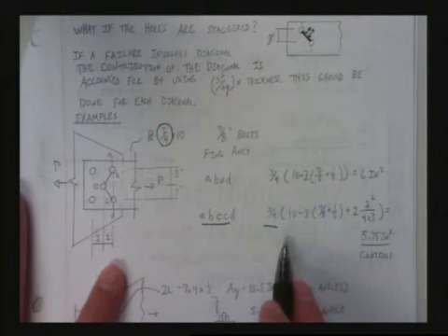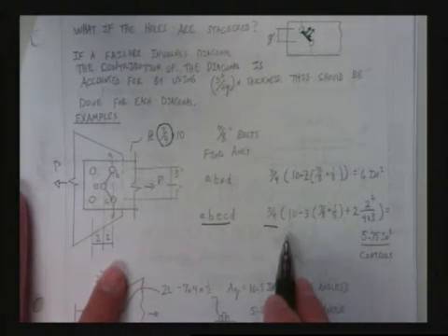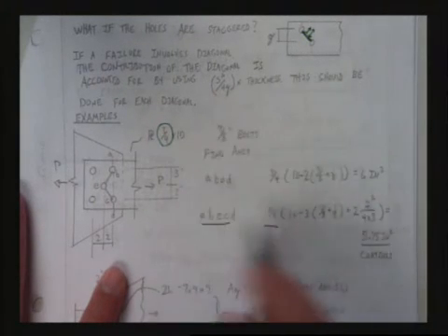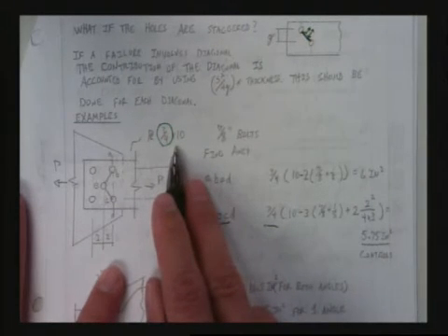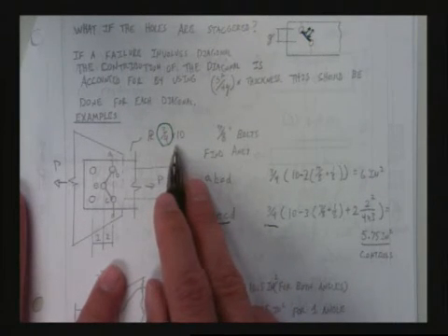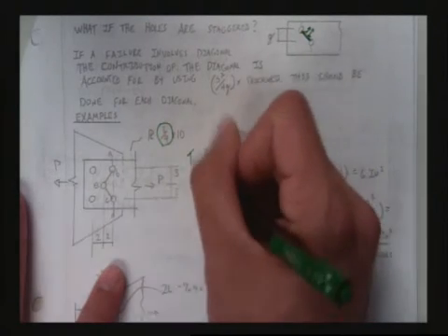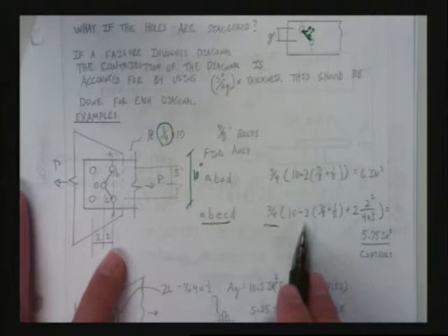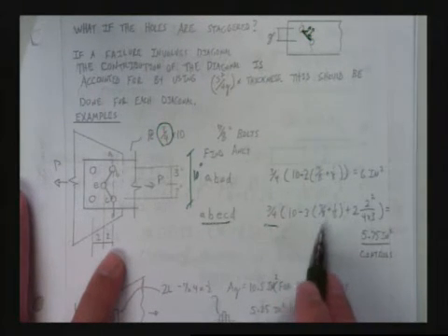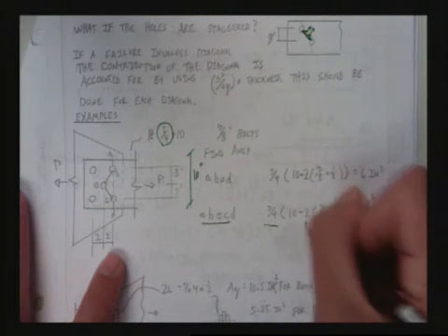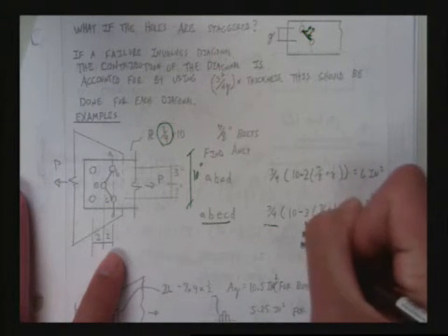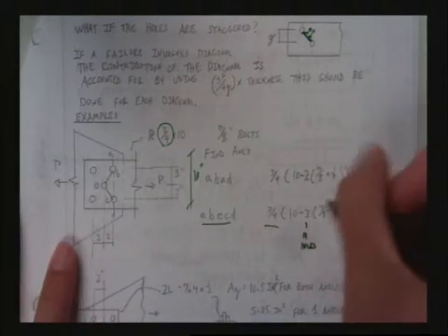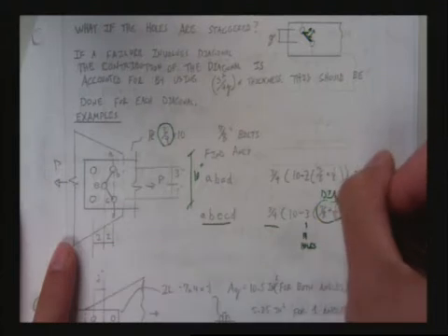We have 10. How do I know it's 10? Well, it's a 3/4 inch by 10 inch plate. So 10 inches is my width. My entire width is 10 inches, minus 3. Why do I have 3? Number of holes. This is our diameter term plus the slop.